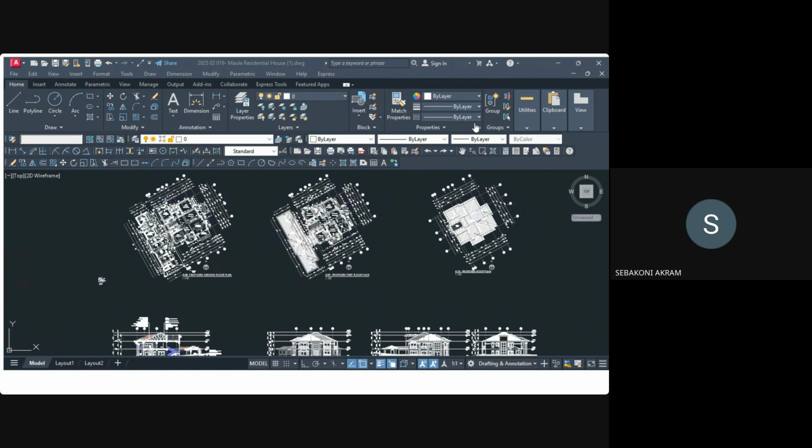We do the load analysis. We have to know what load we have, what capacity we have. Then we head to the supply cables, then we head to the source of the electrical power. So in that way, you're given a residential building from our client, usually the architects or the project managers.